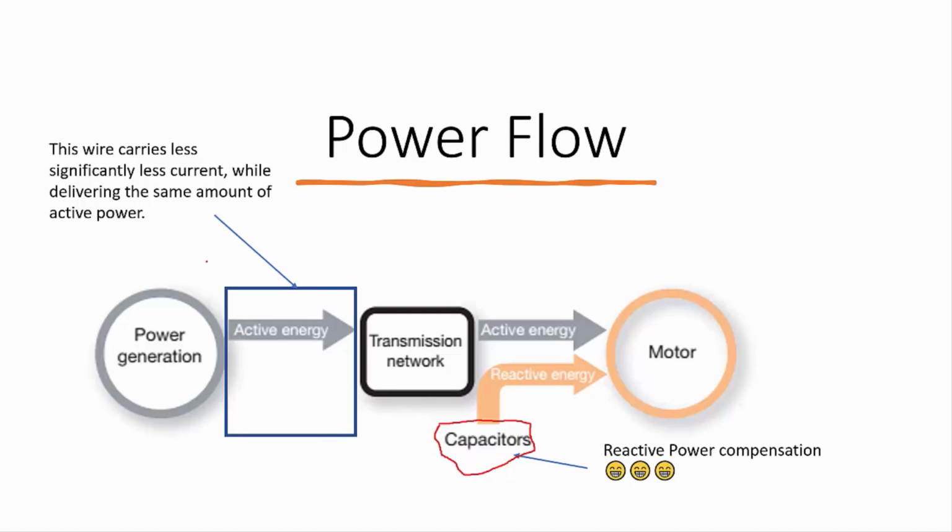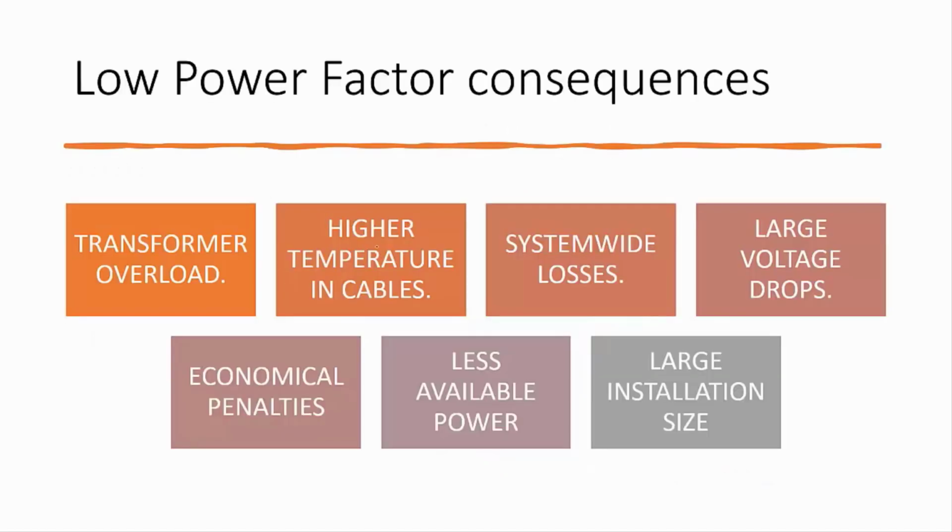And again, there are many factors that contribute to this. But they say, hey, this client is relieving my power lines. This client is being kind to the grid by locally generating reactive power, so I will not fine him, and maybe in some cases even give him a little compensation. At least that's how it works here in Mexico. When you have a power factor over 90, the utility gives you a little something for the favor, right?